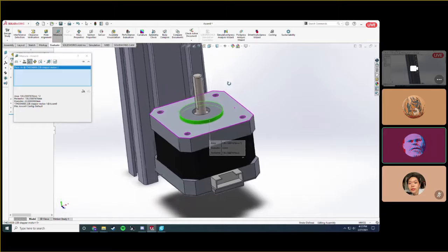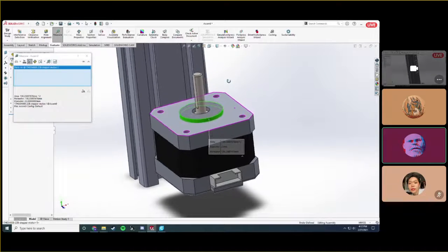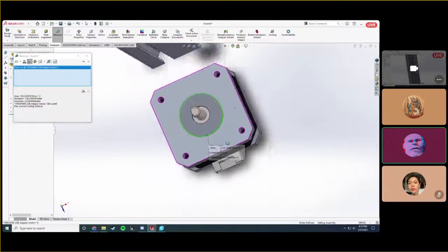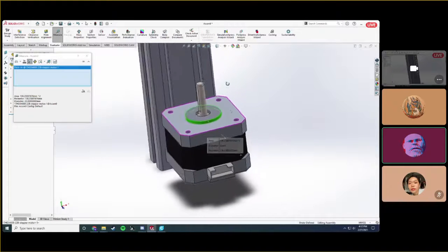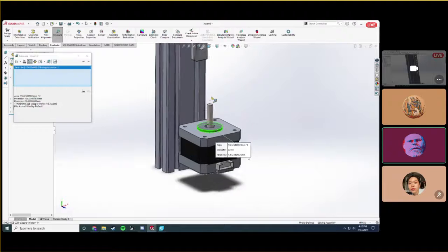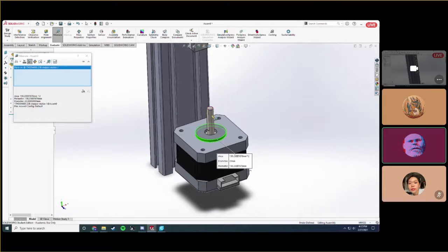Yeah, you have to keep in mind when you design things, especially if you were designing something to be 3D printed, there are certain tolerances that you should be aware of, and your part isn't going to be completely what you design it. There's going to be a plus or minus 0.1 millimeters, plus or minus 0.5 millimeters even sometimes. Depends on how you manufacture it.